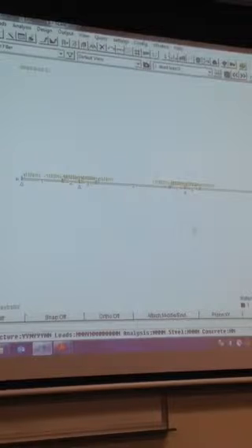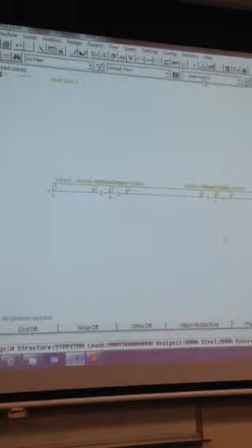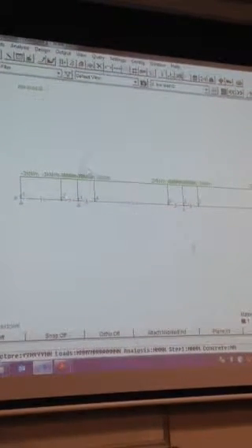Okay. And so it's a bit hard to see because I've put them one over the other. But now if we come up to where it says all load cases, we can separate them out. So it's 1 kilonewton per metre. And up the top here, it's got what looks like a little piano next to the binoculars. So we can actually change that load scale. So I'm going to make it a bit easier to read. So that's a bit better. And then we can look at live load. So my loads are in pretty well, that's good.